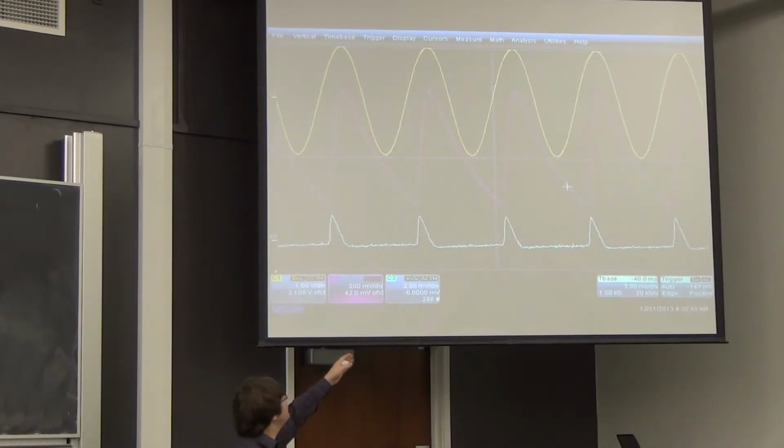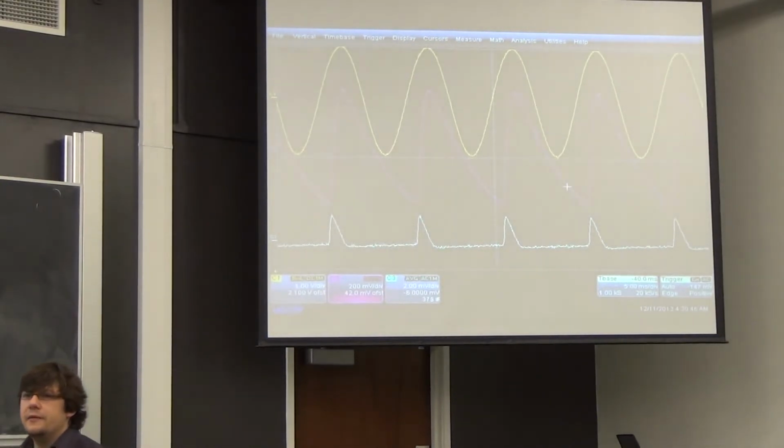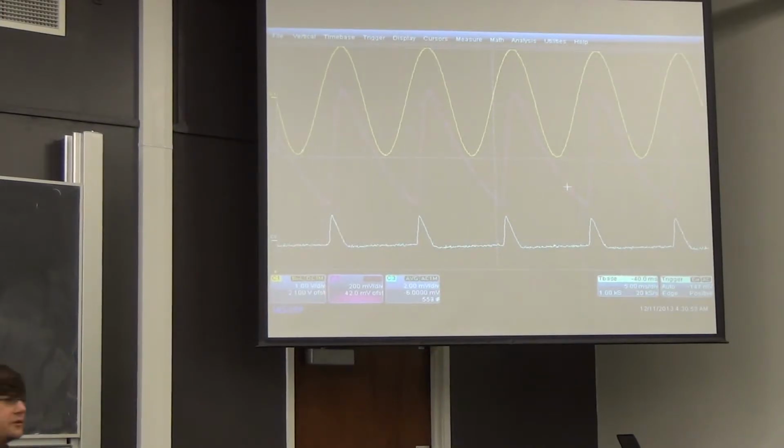The diode switches on, and the current flows to its high value almost immediately. Then, as the voltage on the capacitor rises up to a maximum, the current decays away. It looks almost triangular. Of course, in this situation, the voltage waveform doesn't look triangular. And we can say that the area under that bit is still equal to the area under the spiky bit.